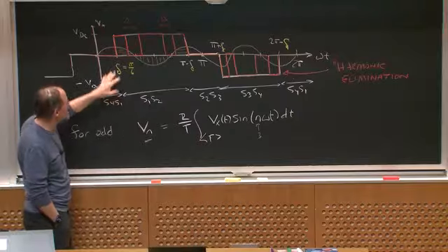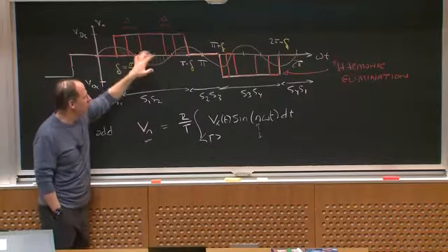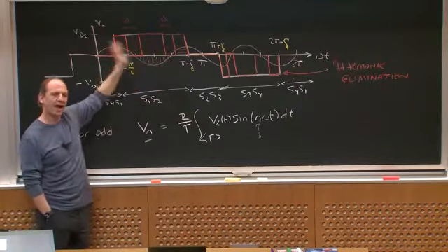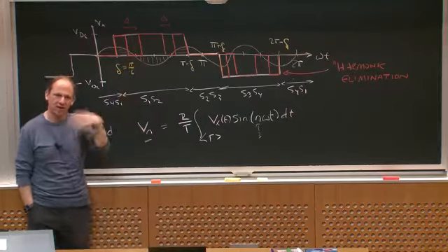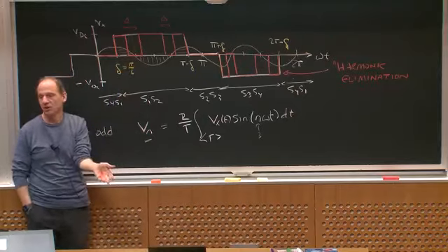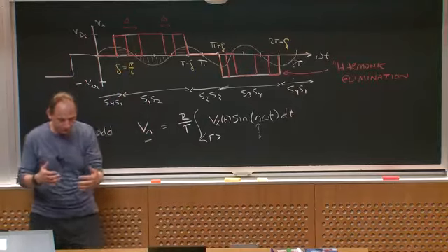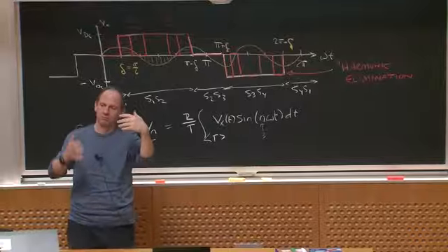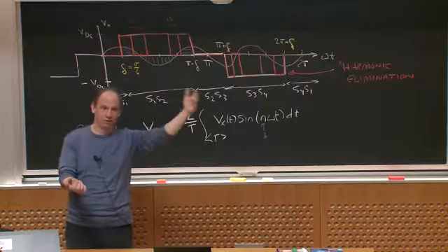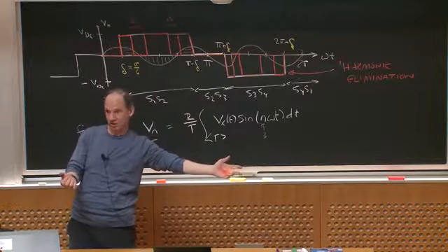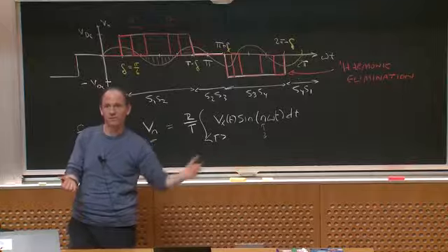Without working it out, each time you get a pulse per half cycle, you have to add on some switching transitions, so you get higher switching losses, right? So what I'm really doing is trading switching loss for lower filtered output components. Okay?